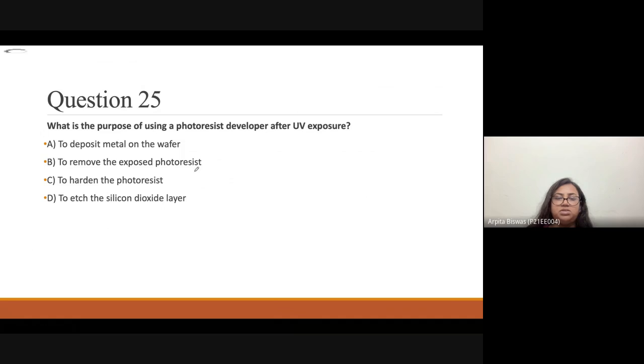We have already discussed the photolithography process, like when we want to fabricate a micro heater or an interdigitated electrode. We start with silicon, then silicon dioxide, and after that we deposit the metal. Then, using spin coating, we deposit the photoresist, and after the photoresist, we go through the UV exposure, and after the UV exposure, we go through the development process.